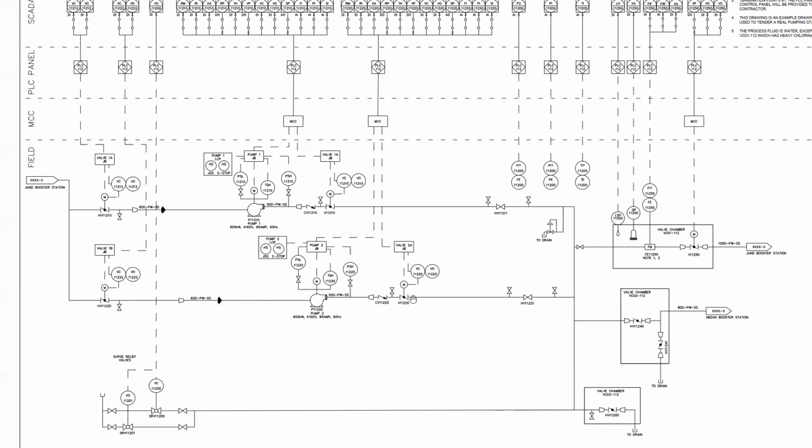of that size, there's probably 4 or 5 different solenoid valves to make sure it moves, and like 8 for every solenoid valve. So there's 4 of them. There's going to be 2 needle valves on either side of them so that you can calibrate the solenoid valves, plus a few drains and a bunch of pilot lines for safety. That's not really sustainable on a drawing at this kind of level of granularity for what we need. Does that make sense?